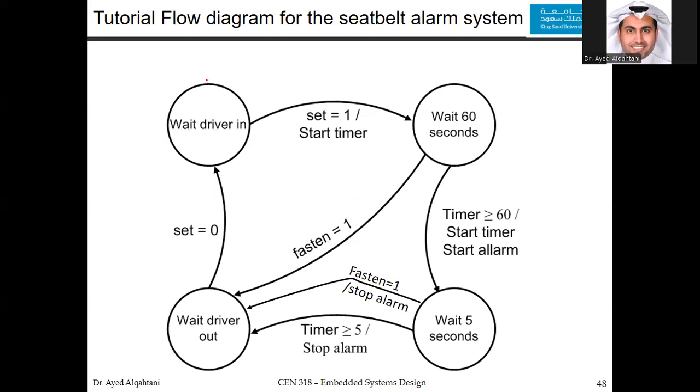The beginning, the first state, you can name it anything, but here I give it a meaningful name. In the first state, you wait for the driver to get in. So if you are in this state, it means that you are still waiting for the driver. Now if you are in this state and then sit becomes 1, meaning that the driver sits on his seat, you move to the second state, which is waiting for 60 seconds.